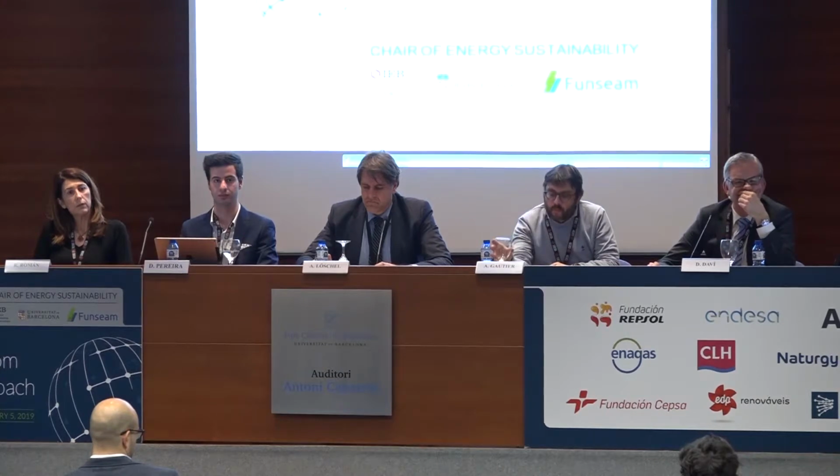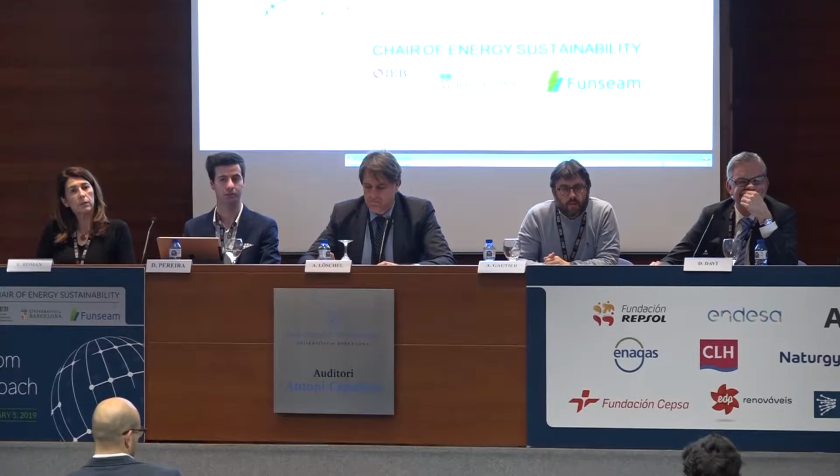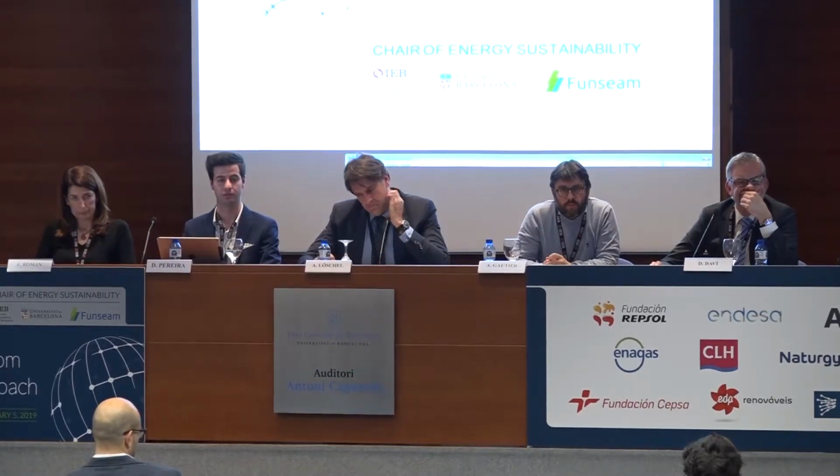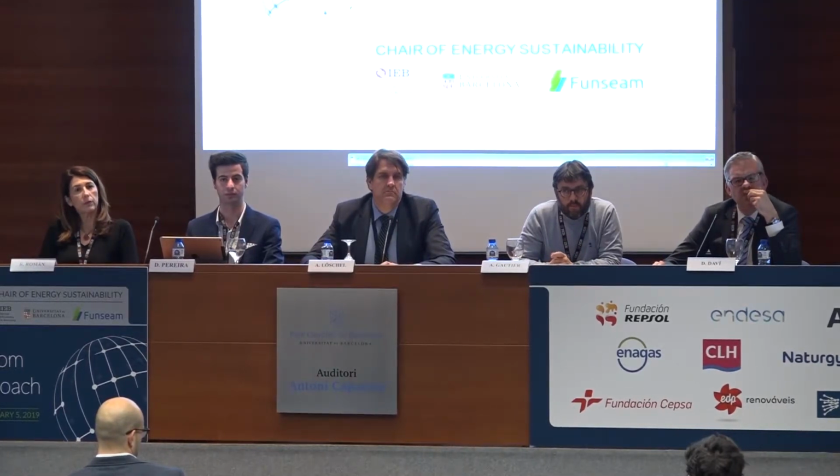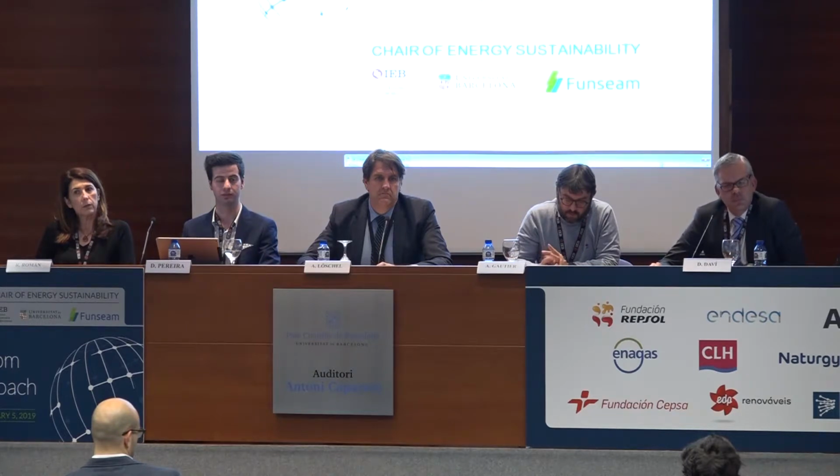So I'm more familiar, you talked about optimal flow. So this PTDF, for example, I just looked up the abbreviation, power transfer distribution factors, where you have a physical network and you have to account for loop flows. The question is to what extent you can capture relatively established models with what you have as a new approach, the gravity model, which has hardly been applied. Maybe the reason for not applying it is that it could be a bad proxy to think about how injection at some point affects the whole flow, because you have this loop flow aspect. So it's not enough to just put a network and keep that static, but you have to keep the real physics in the model. My suggestion would be at some point, you could compare your model with some engineering type model like the PTDF, for example, and see how good your proxy is.